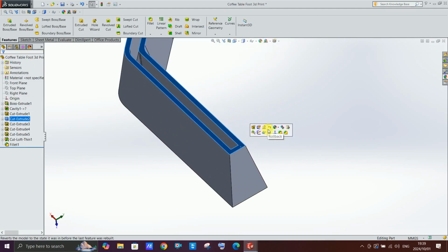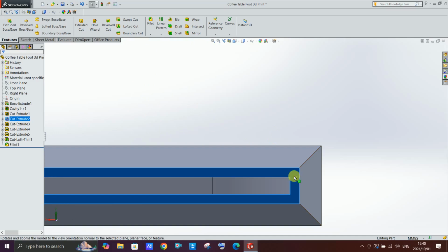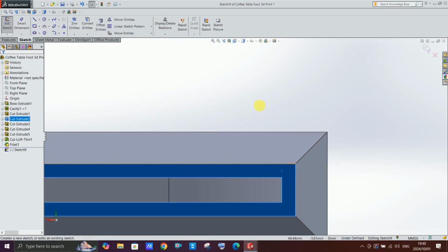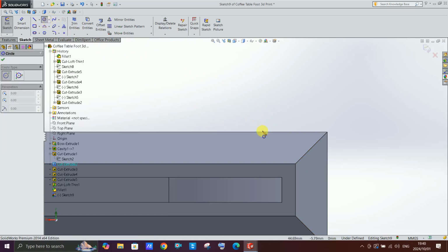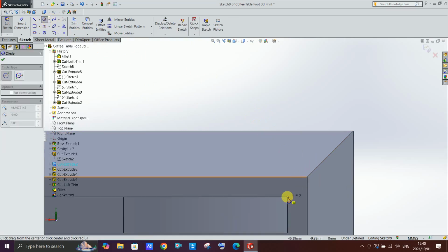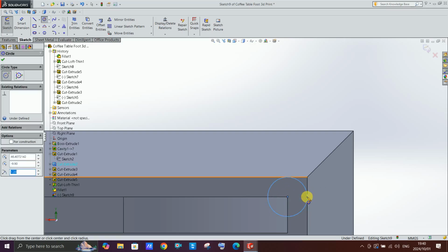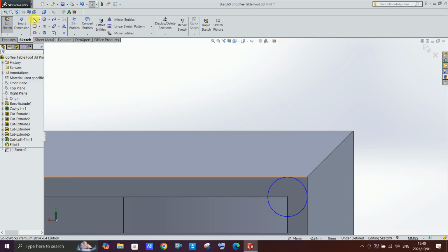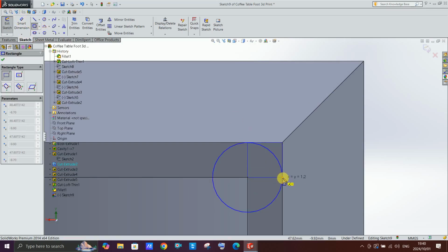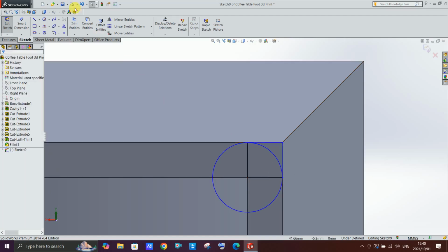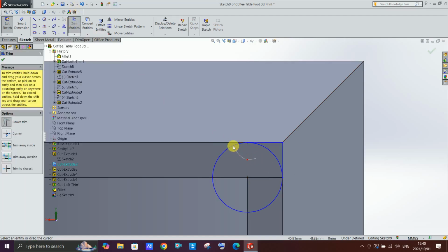you select the top, normal 2, and then you sketch. Okay, then it's a circle. Then from this middle point you select the edge. Okay, and I can actually do the square. Square will be much easier and faster. And then you just remove the excess.